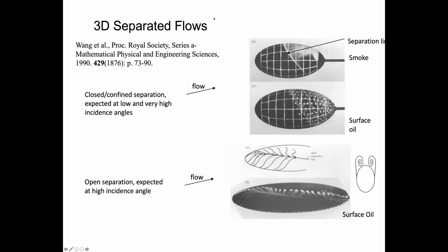This domain, if I can annotate, is really a nightmare to deal with and model, and will be sensitive to Reynolds number effects, and RANS modeling of this is going to be quite a challenge. What really happens here, because you have two stream surfaces that meet each other? Anyway, that will be fun to investigate. I don't have the slightest idea where it would occur at high Reynolds numbers. So this is why I wanted to develop a system that will allow us to move the PIV system as close as possible to the leading edge of the model.